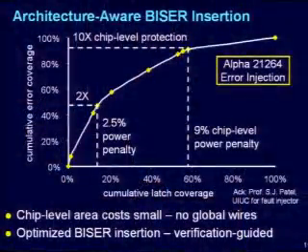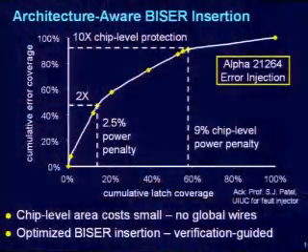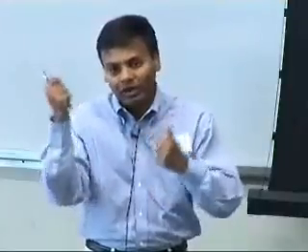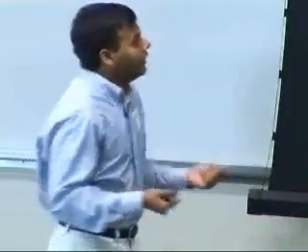So what's the cost of doing something like this? Of course, at the flip-flop level, let's look at power cost first, because that's what people care about the most. And then we'll talk about area costs. At the flip-flop level, I have two latches that are transitioning, so of course I'm going to have 2x the power. I cannot do anything about it. But again, nobody sells flip-flops in an actual design. Everybody sells a full design. So we looked at the Alpha processor because it was open source, and we got hold of this error injector that Professor Sanjay Patel at Illinois developed.